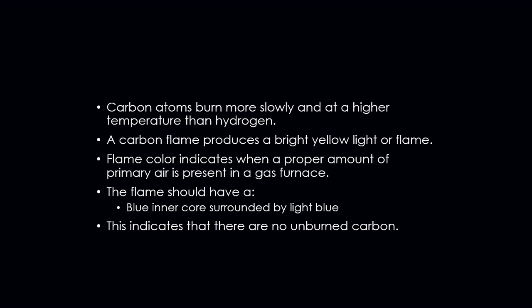So carbon atoms burn more slowly and at a higher temperature than hydrogen. Remember, carbon is a little bit heavier. The carbon flame is going to produce a bright yellow type flame. Okay? Think about an oil-fired furnace, if you've ever worked on one of those. When an oil burner fires off, that flame is a little bit more of a yellowish-orange color. Natural gas is going to burn in a more bluish color.